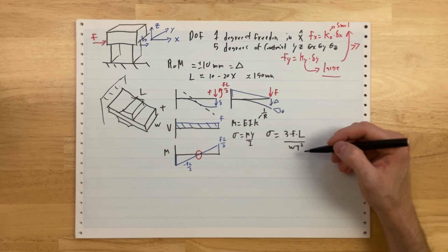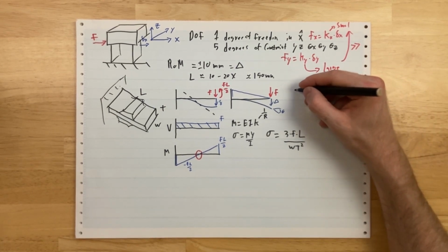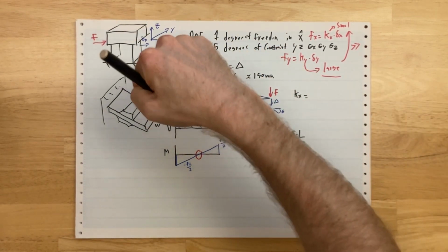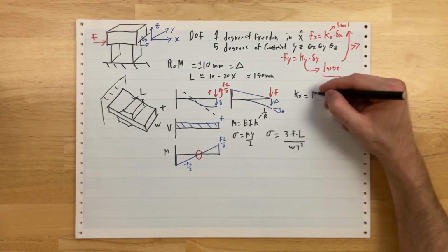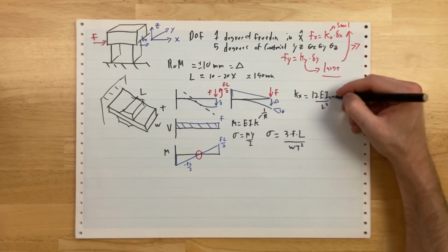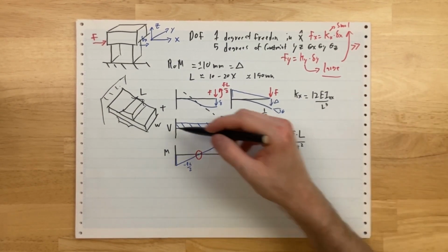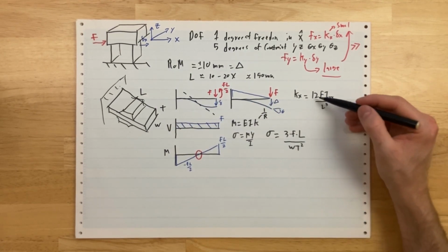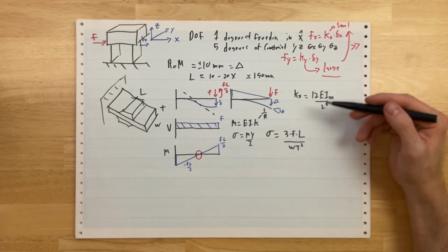Well, I actually need to pull out the beam stiffness to do this. So I'm going to go to Kx. Basically, the force it takes to push out of plane is equal to, wait for it, 12 EI over L cubed. And this is Ixx, the second moment of inertia in this kind of bending direction. And if you remember, your cantilever is like 3 EI over L cubed. This is actually 4 times as stiff. You can find this in handbooks. You can derive it yourself, whatever makes you happy.